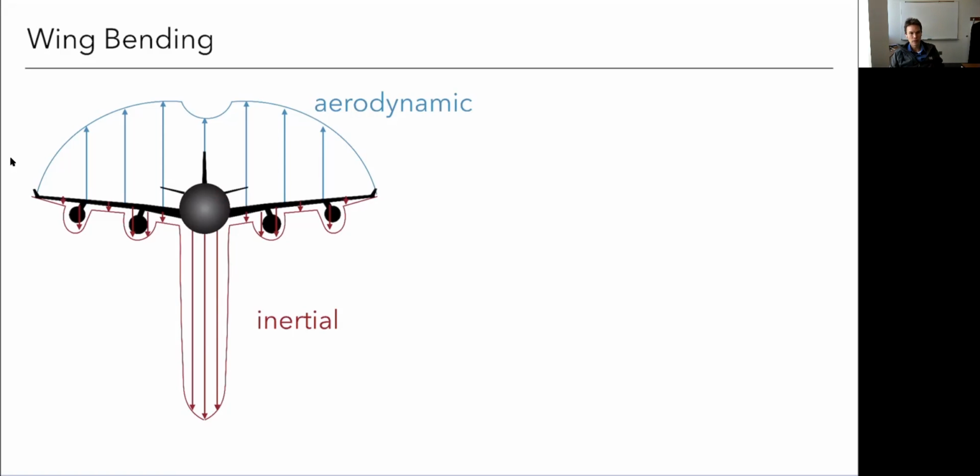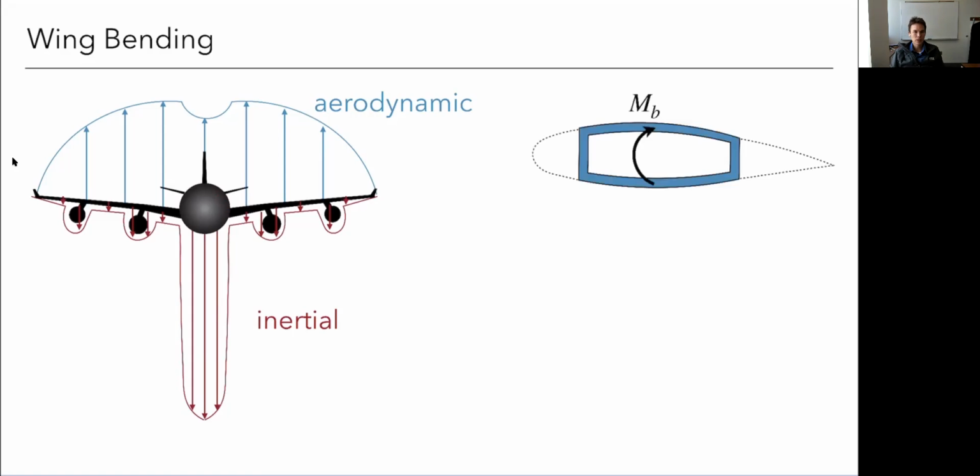And we'll see a video of that in class, but here's a picture of that bending moment. So again, imagine my wings are bending. Which side is in compression, which is in tension? Well, if my wings are being bent up, as will be normally the case for 1G flight or higher G, this top surface of the wing is in compression, this bottom surface is in tension. That's what's depicted here on the right. This moment is pushing on the top compression, tension here on the bottom.